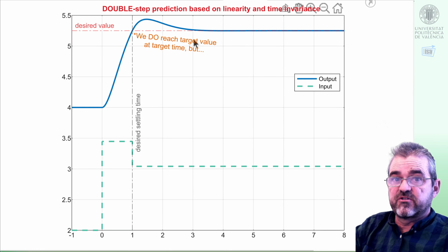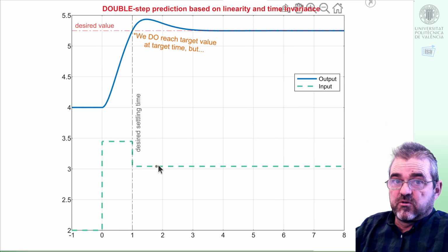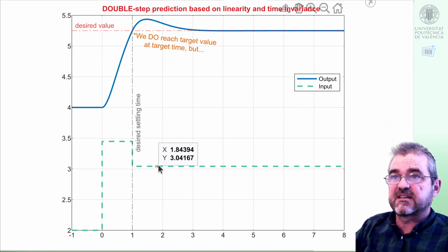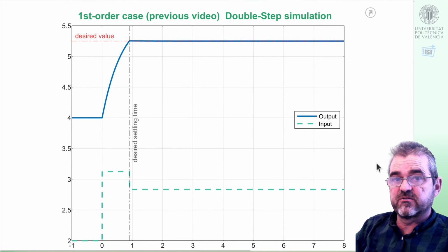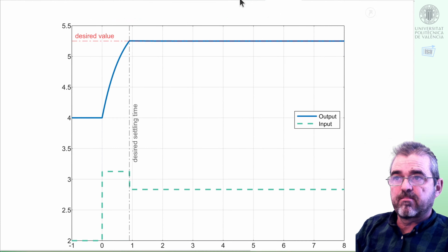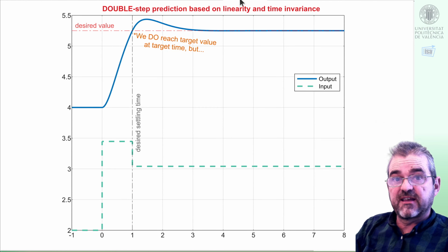But well, if this overshoot is somehow acceptable in practice, this may be a good solution, but it's not as accurate as when we computed that with a different system which had no inertia, a first order one, and then the system instantly stopped at the desired value. But a system with inertia cannot instantly stop without, say, an infinite acceleration.